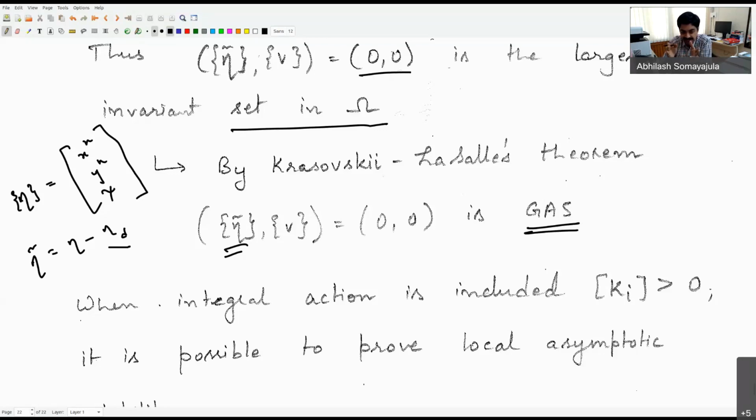So, but there is a caveat here, okay? We did assume here that eta_d is constant. But now we are trying to apply it to things where eta_d need not be constant. And yes, it will work there as well, but there may be some stability degradation which may happen. So that's why we have to be a little careful about it. That part definitely does exist. And in fact, you'll see, forget about all that. The moment I add integral action itself, this stability cannot be guaranteed.